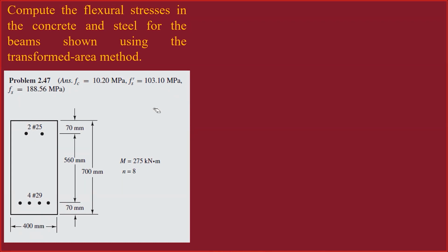So how do we solve this? Clearly it is doubly reinforced. This type of problem is actually an investigation, because you already have the design of the beam, the dimensions of the beam, and you are to evaluate the capacity.